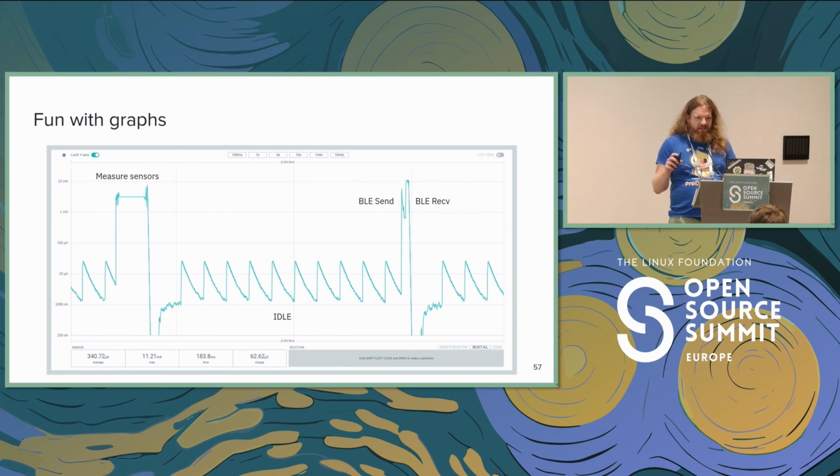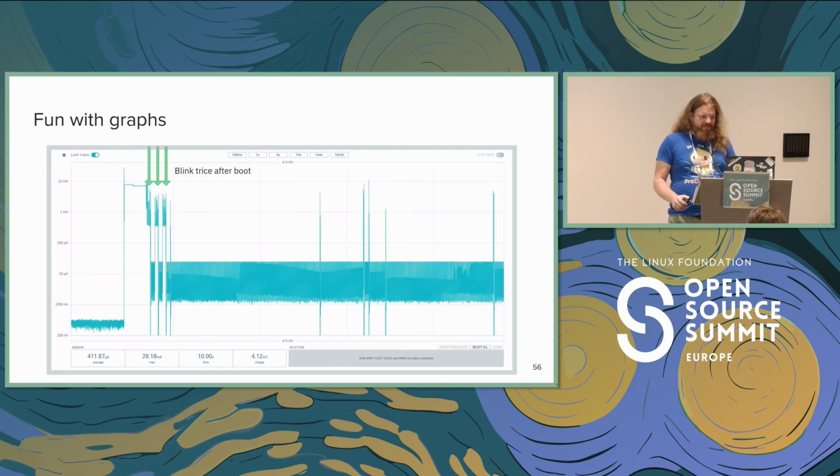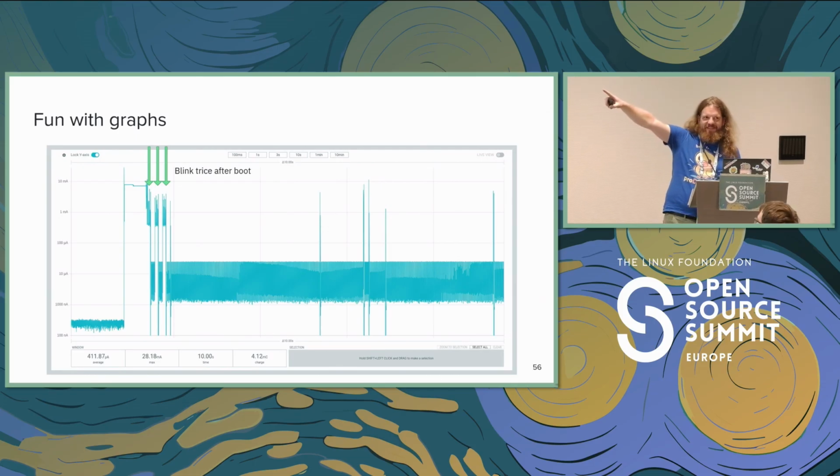Yes, there's support for shutdown in some of the CPUs, but you have to call shutdown explicitly. But if we go back one slide, after shutdown you have to wake up again and do the initialization, and the initialization sequence is really power hungry compared to everything else in the graph.